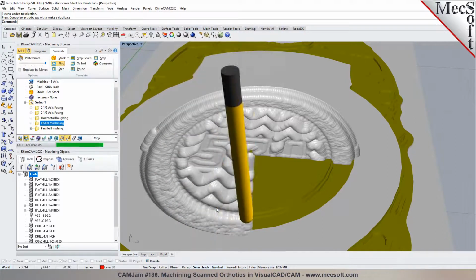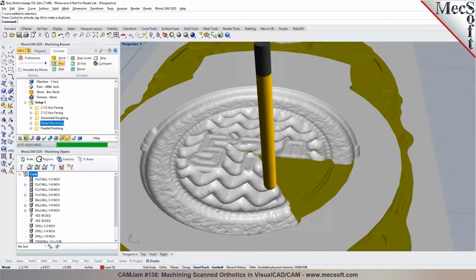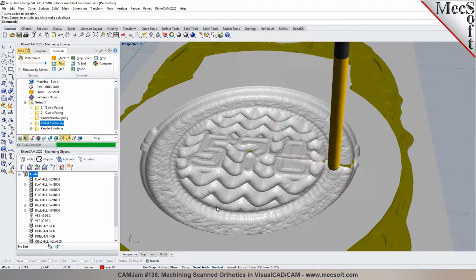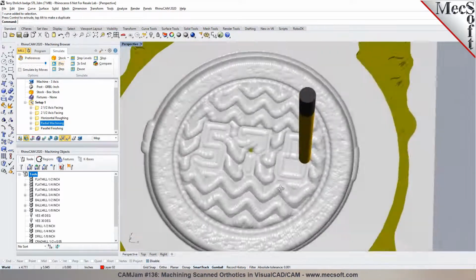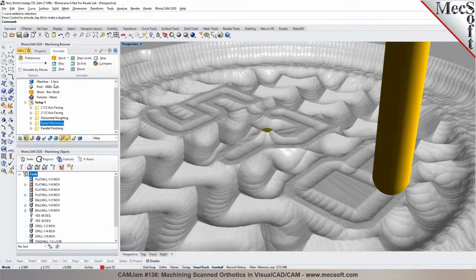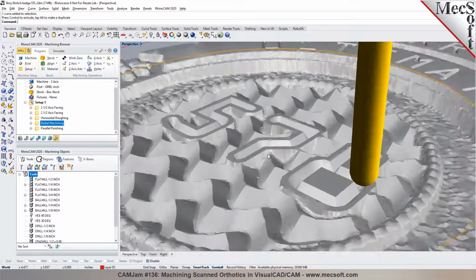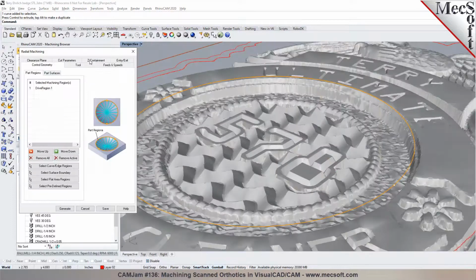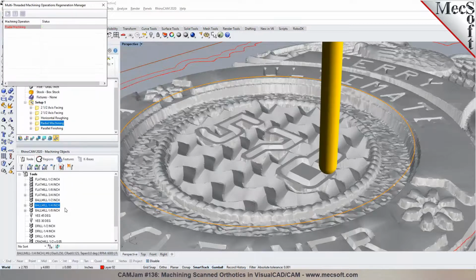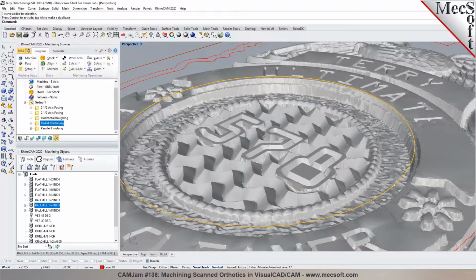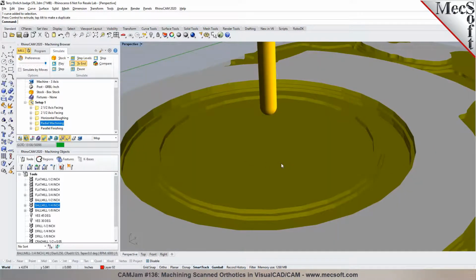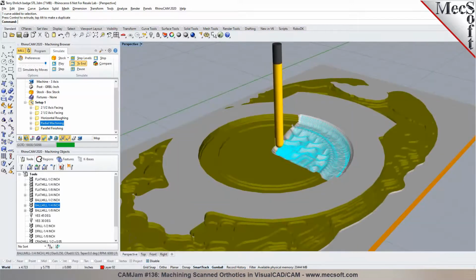So there's different ways you can program it. The circle I drew was just to use as a containment. We could also do spiral machining. We also have horizontal or Z-level finishing, or constant Z-level finishing as well. Okay. And if I had specified it to leave a little bit less radius in the center, I can make this just 50 thousandths. And all I do is regenerate the toolpath, and I can do a simulate to end. That's going to run through the simulation from start to finish.